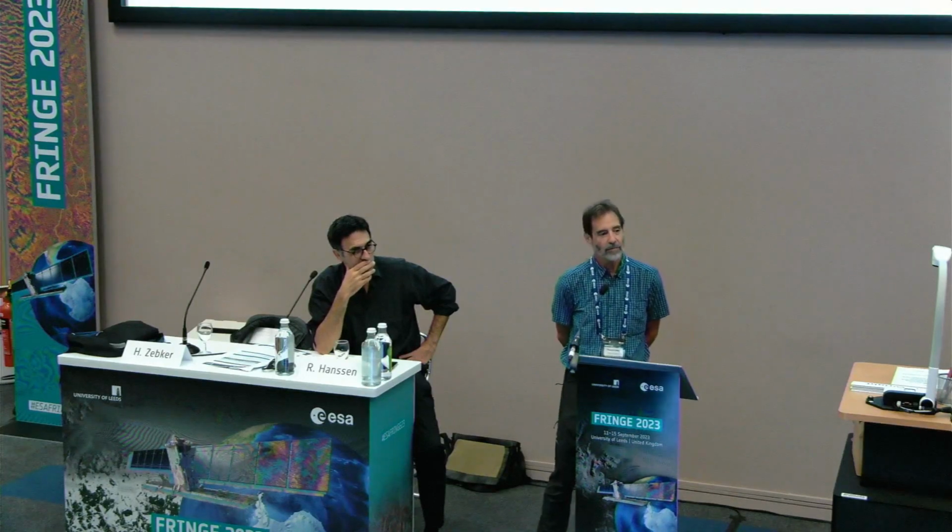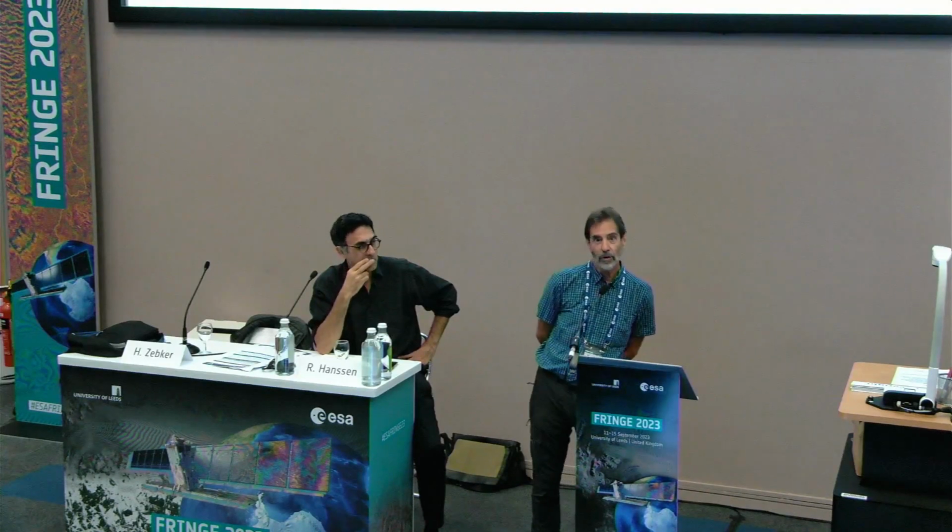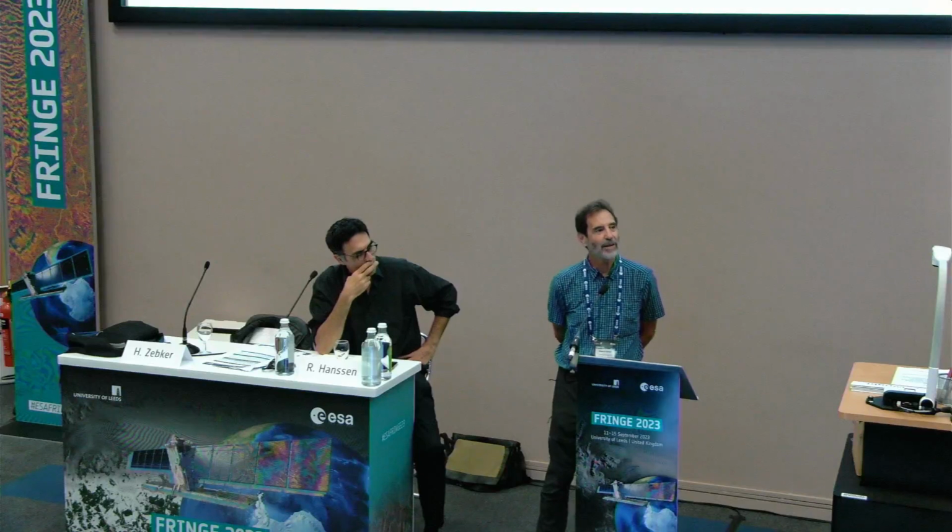So if you have deformation between those big points that are not adequately sampled with a PS point, yes, you won't see it. So you're stuck making a best guess. You could just multiply the output data by the PS mask and say, here's where I believe the data, and we'll just ignore the rest of it. But we all have many, many analysis routines for working on spatially continuous data.